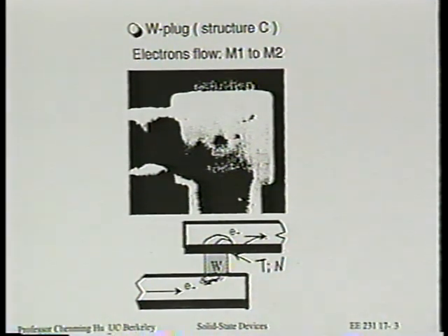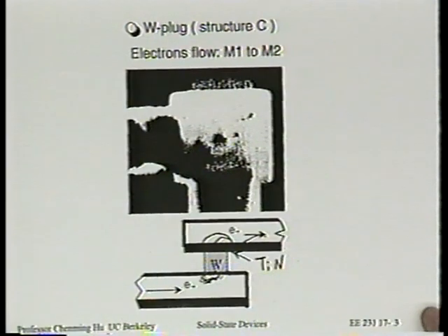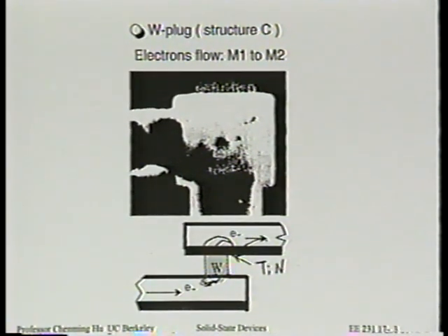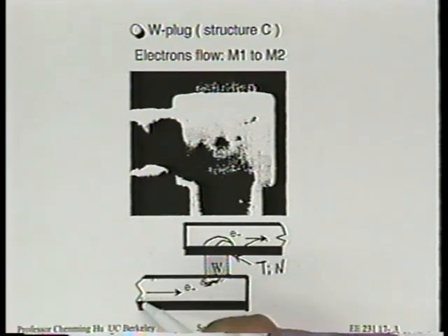Okay. So therefore a refractory metal as a liner between the tungsten via and aluminum is very commonly used. Now I give you this example, electromigration at a via, not because that's the only place where it can happen, just because it's easier to understand why it happens here. In fact, it also happens in long lines. In fact, that's where people mostly are looking.